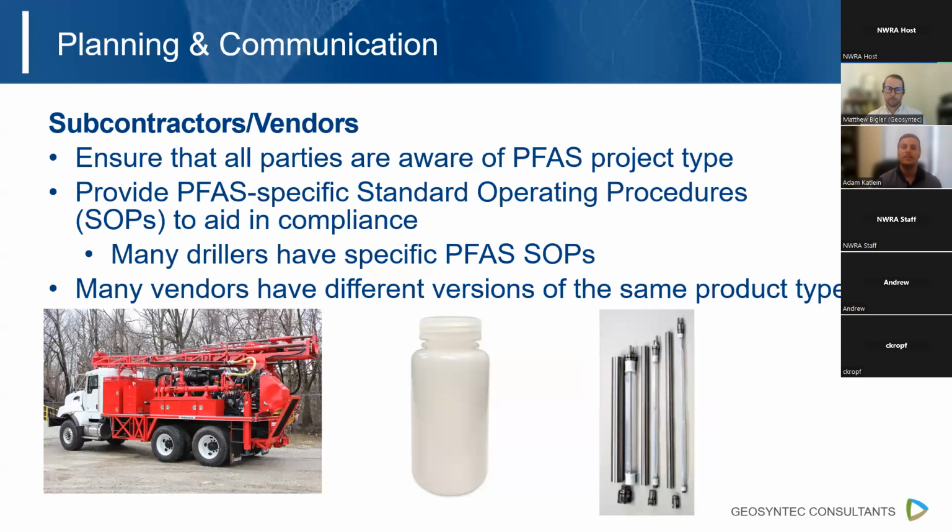Things like with pumps, you can have the same pump that you are used to at petroleum sites, and they'll have a PFAS-free version of that, where it's just a bladder, for instance, that's PFAS-free, or for instance, hydrosleeves where they'll use HDPE instead of LDPE. So there are options available now, but you just have to do a little bit of research on the front end, basically. Next slide.